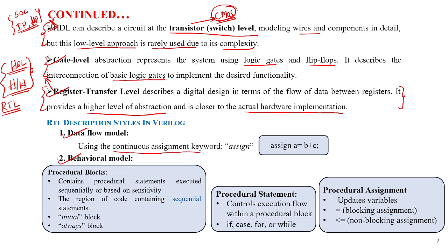This is a continuous assignment statement. You need to use assign. Suppose these will be expressed in terms of expressions. Suppose a half adder is there, which you already studied. Sum equals A XOR B, and carry equals A AND B.